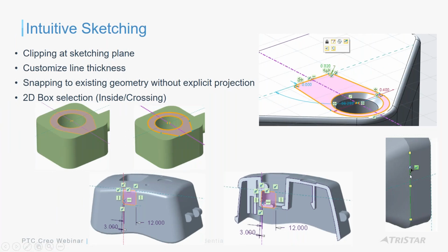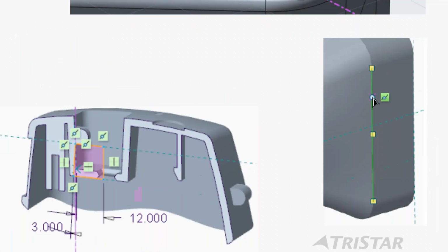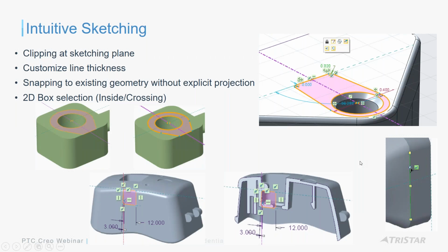They use the same commands. To add references, all you have to do is visit the geometry, and when you visit the geometry, it will quickly add references. You could add references with the Alt key. However, just for example, in here, as I'm sketching, I cursor over this edge, and it understands to give me a midpoint guide, an end guide, and a guide here, so I can quickly snap to that geometry while sketching. So much better workflow, right?